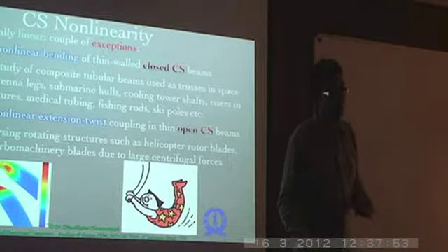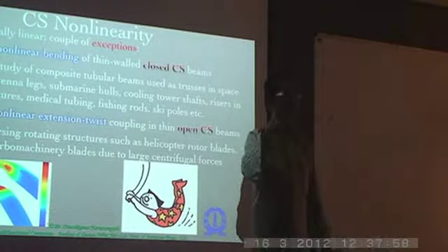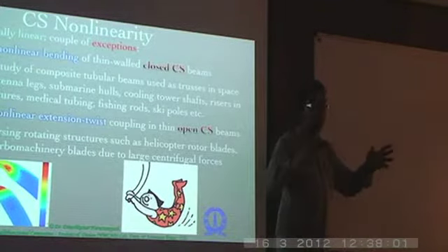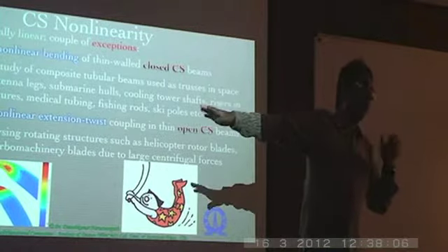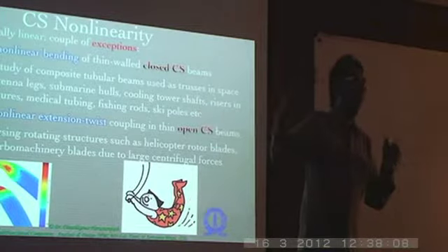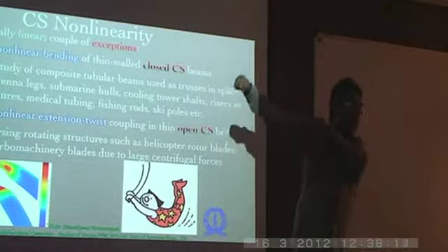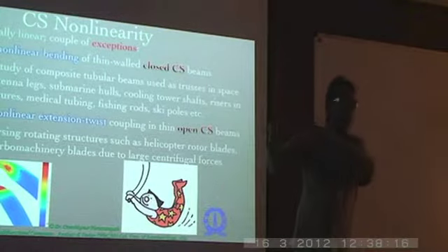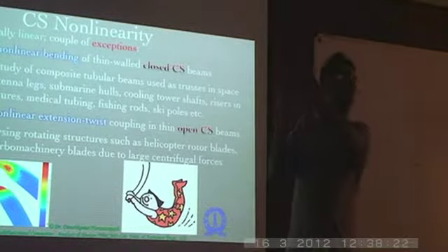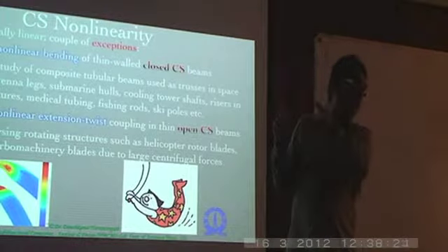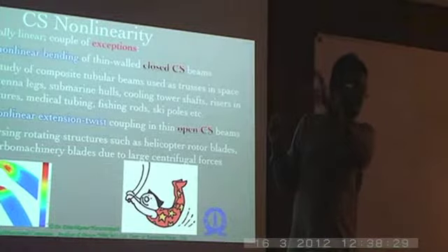Roughly which metrics will go for this wing analysis? A wing basically is like a closed cross section. Again, it depends on the class of aircraft also. But let's say if you're talking about a low aspect ratio, low speed aircraft, for example. Then you basically have predominantly the bending loads which are coming because of the lift distribution, and bending load because of the drag distribution. Again, depending upon the location of your aerodynamic center, which is quarter chord, you have your lift and moment there, and there's also pitching moment depending upon whether you have camber or not.